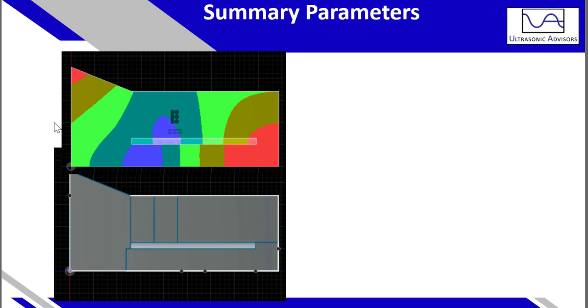So here's actually the mode of interest, at 50 kilohertz, where we get the most oscillation at this end, where we would then attach it to a different substrate. Hence the resonance behavior would change slightly, but it's mainly still dominated by this structure here. Analyzing this transducer in and of itself, let's talk about a couple of factors.